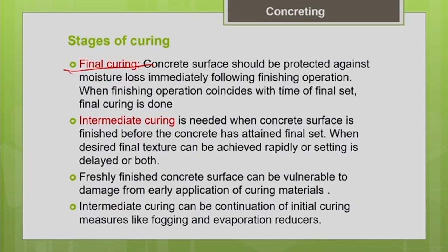So, the ideal case is your final finishing will be coinciding with the final setting time. Once the concrete has attained the final set, you can easily apply the water for the final curing. There the concrete will not get damaged because of the application of water. So, that is the right time to apply. After the final finishing, after the final setting of your concrete, you can apply the water to do the final